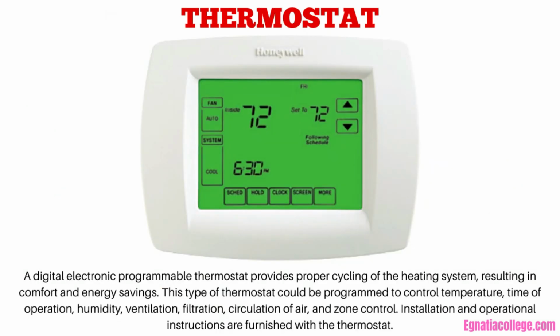Thermostat. A thermostat turns the heating/cooling system on and off. Programmable thermostats might have day or night setback settings, temperature, humidity, and time displayed. Thermostats are usually mounted about 1.3 meters above the finished floor. Do not mount thermostats in areas influenced by drafts or air currents from hot or cold air registers, near fireplaces, near concealed hot or cold water pipes or ducts, in the direct rays of the sun, or on outside walls.